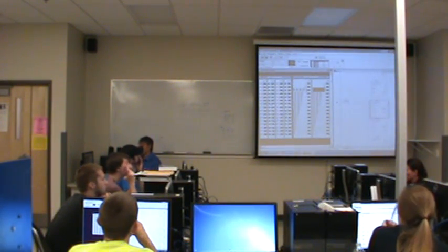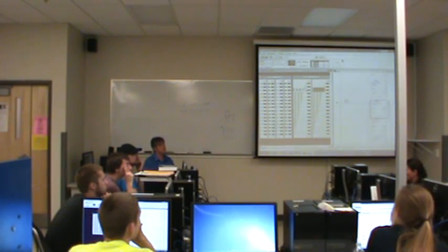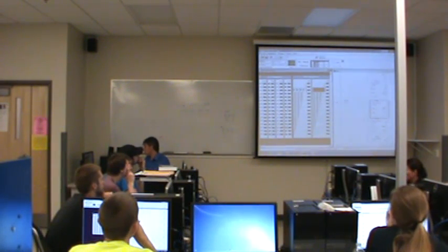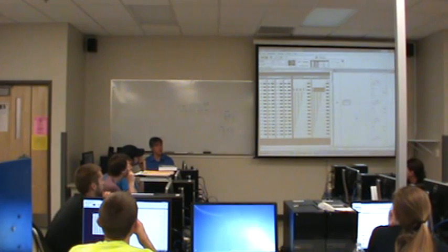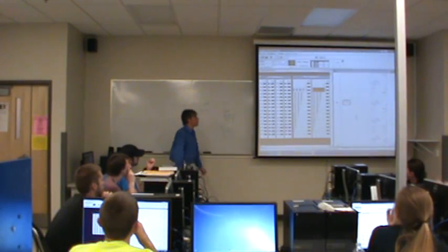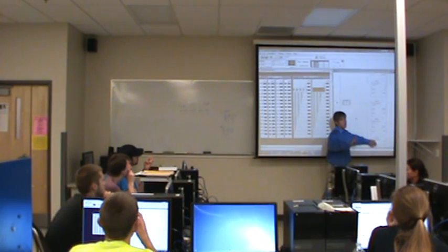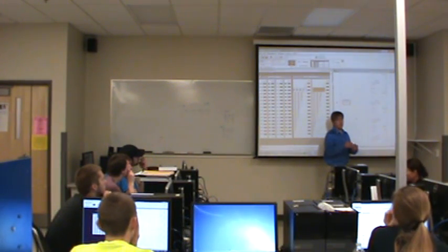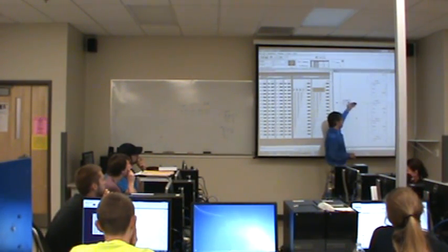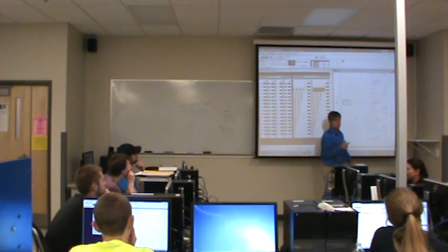I have a question. Sure, please. That OSR operation, what's that? I was about to describe that. OSR is a one-shot rising. It's kind of misnamed. Basically, I only need to put this data in memory once. Once the program starts running, I just want the data copied. I don't want to waste scan time with this every time I go through.